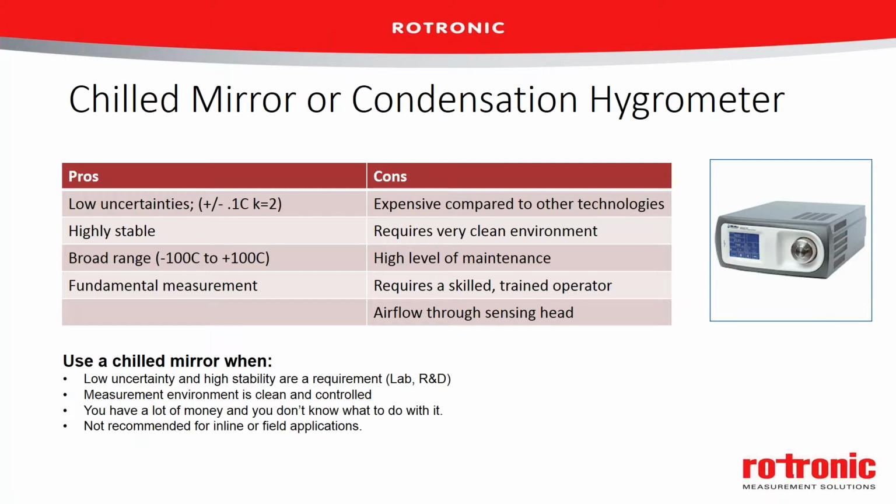These do require a fairly clean environment. If dust or other particles are landing on the mirror, there's no way for the mirror to know the difference between dust or water vapor. Some of them have some tricks to try to make that determination, but it is important to keep that mirror clean.